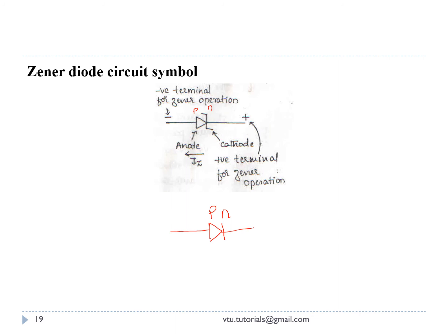Usually this Zener diode will be operated only in reverse bias. So the external voltage supply can be mentioned like this, with P type connected to the negative terminal and the N type connected to the positive terminal. And this again shows the conventional current direction in the forward biasing state. In forward bias, as usual in the PN junction, it is the conventional current direction. So here it remains the same.